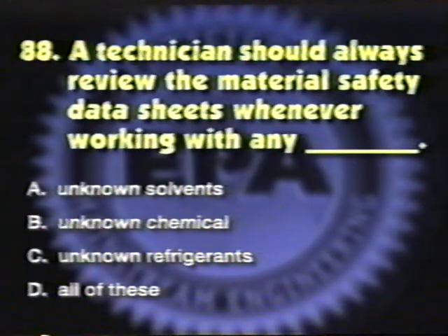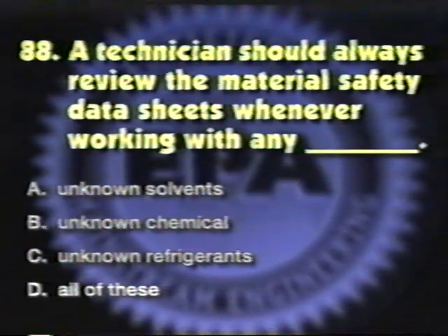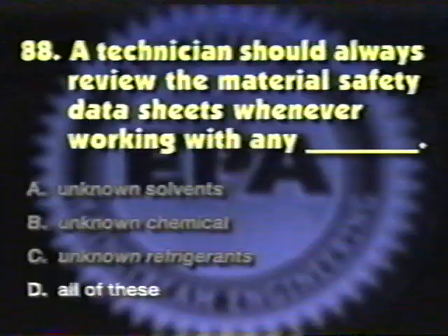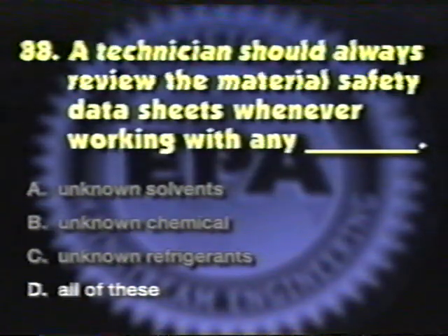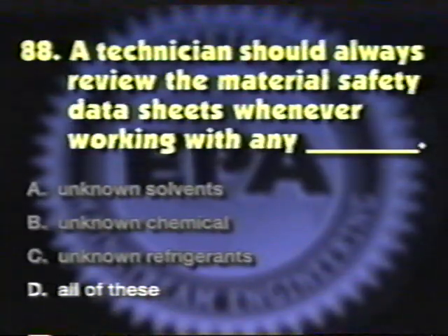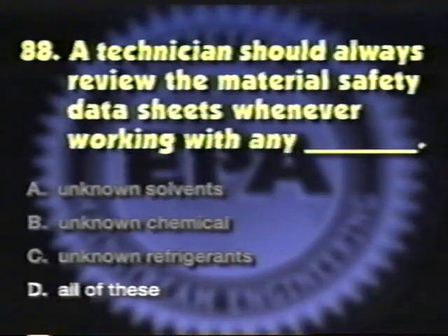The correct response is D. Whenever a technician is working with unknown solvents, chemicals, or refrigerants, the technician should always review the material safety data sheets, which by law should be shipped by the manufacturer with these compounds.